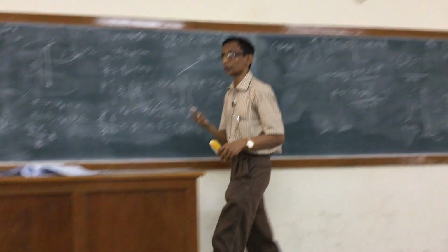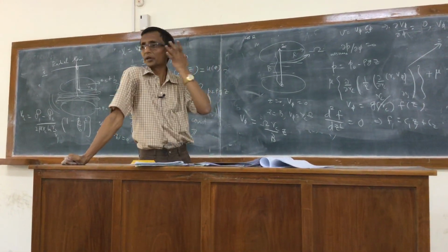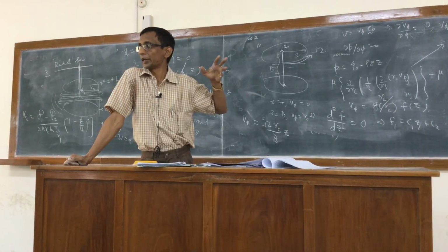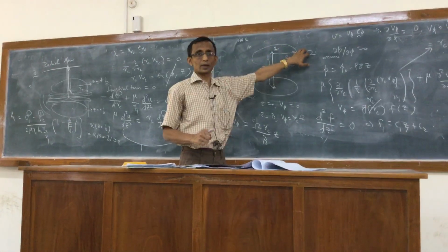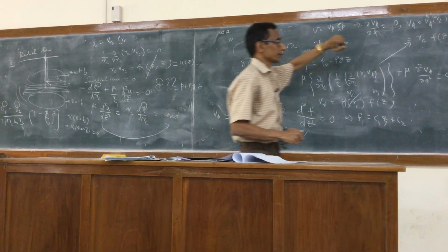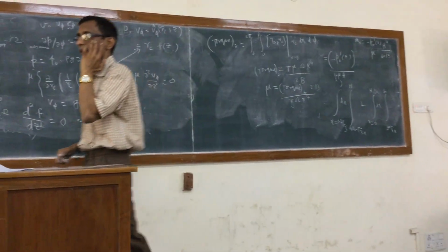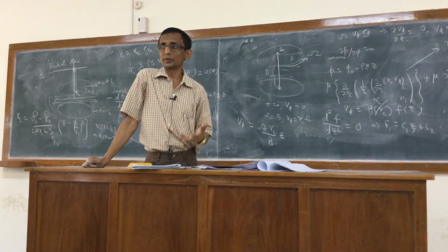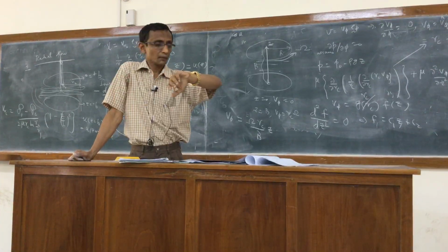So by measuring the torque, what Bird would say is that this is the way of measuring the viscosity. We measure how much torque mechanically we should apply to rotate the top plate with some angular speed omega, which can also be measured, right? And then how much torque we should supply, and then we can determine the viscosity. But it goes with all these approximations. So if these approximations go through, then this is a good way of estimating the viscosity.